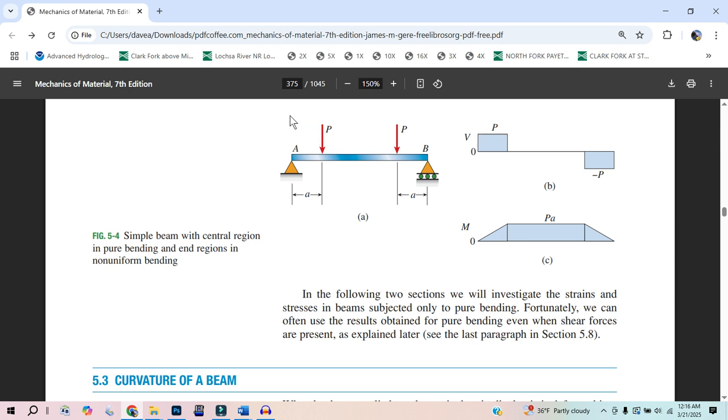So here's another way to look at shear: let's take this and pretend it's a slinky, and each of the slices would be a little bit lower. And that's what shear does, especially if shear is positive, you're going to have just a linear displacement. So if we did see a displacement due to the shear, it would just be exactly that scenario I just talked about with a slinky. You just have a constant slope.